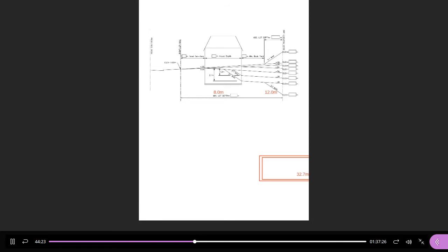No. Okay. There's a reason for that. The maximum allowable slope is 5%. If you use 5% to design your side yard, the side of the lot, the edge of the lot, you're going to cause problems internal to the property. Okay, and we're going to do some math together. I'm going to show you exactly why.